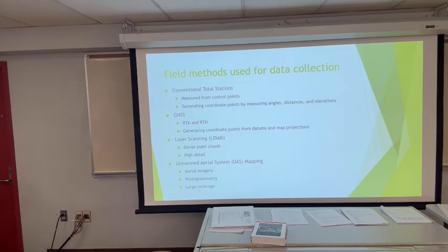So with the GPS, you're using a couple different ways, the RTK and the RTN. Those are two methods of collecting. The RTK is real-time kinematic. You have a base set up on a known control point, and you have a rover going out on it, randomly, real-time picking up positions. Both your receiver and base are collecting satellite signals. The base is also sending some corrections and information based on its known point and updating the position of the rover real-time.